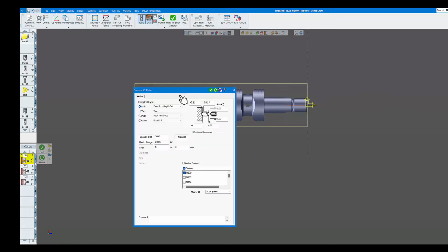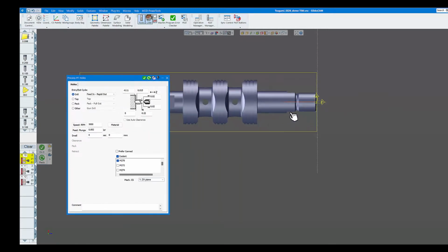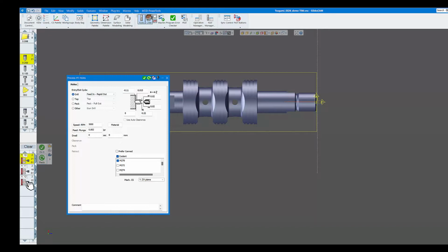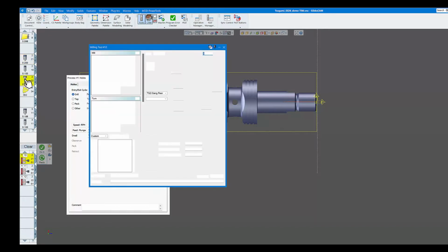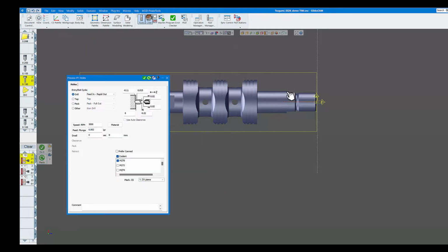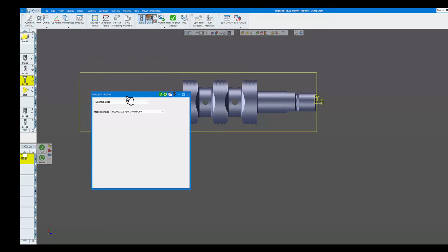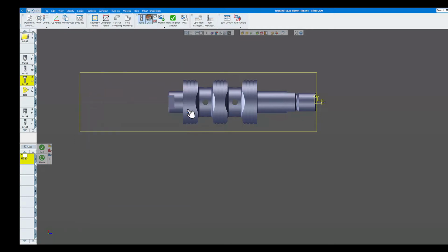Then our next operation on spindle number 1 is going to be drilling. We're going to use tools number 10, 11, and 12, which are a 1/4 inch spot drill, then a drill, and number 22 is going to be our tap. That's the next operation in our list, so we can just click on redo that. The next process is going to be sync control off. So we're done with simultaneous drilling with flow 1 and flow 2, the front and back.